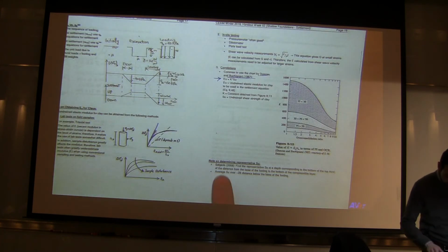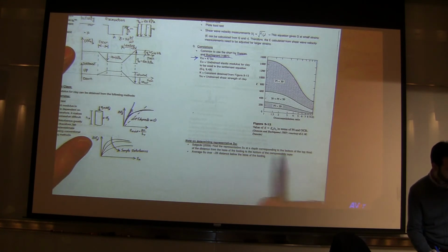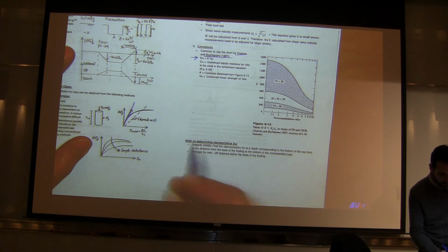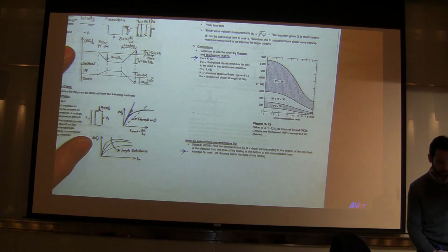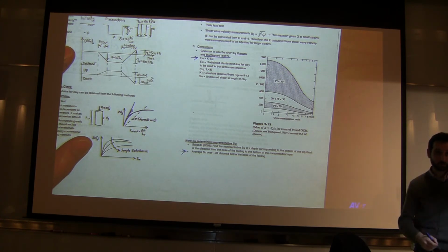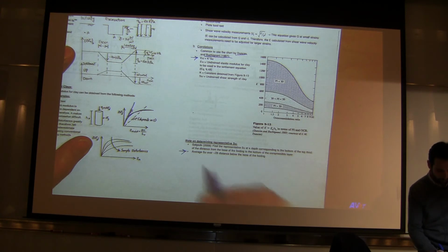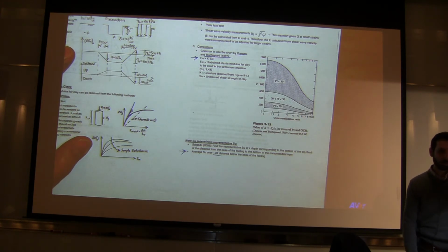So in fact, if you read here, I have what Salgado listed for averaging SU over. It's a little more complicated. What I would go with is this. I think the Salgado approach is too much. It's splitting the hair. We have other uncertainties in these methods, and that's too much refinement. I would just go with that 2B distance below the base of the foundation.